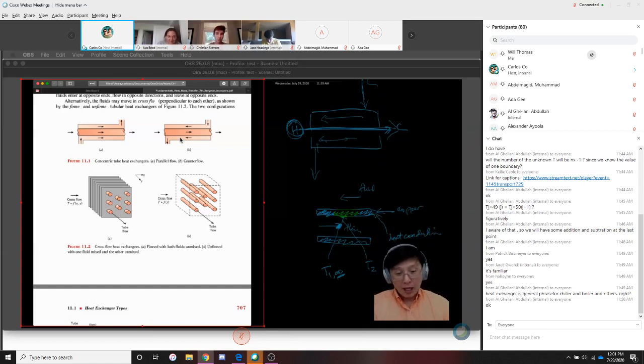Okay? And so the heat conduction is characterized by a thermal conductivity of the copper material, right? The heat transfer in the fluid is governed by a heat transfer coefficient, that in this case will be T1 infinity minus, let's say, T2. Within this copper wall, the heat flux is going to be minus k times the derivative of the temperature. And because this is a cylindrical geometry, you're going to have a 1 over r derivative of r dT/dr.